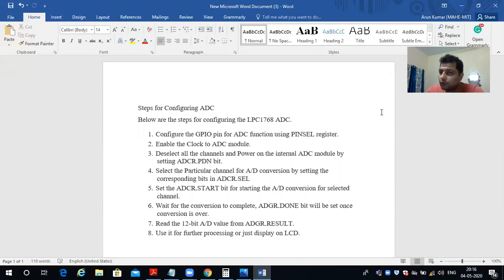In the first program, the software control, we will use AD05, that's the fifth channel, and that corresponds to pin number 31 of port 1. So P1.31 corresponds to AD05 and P1.30 corresponds to AD04.